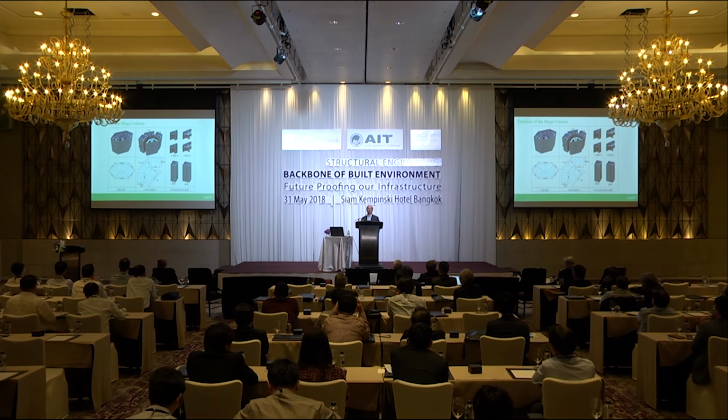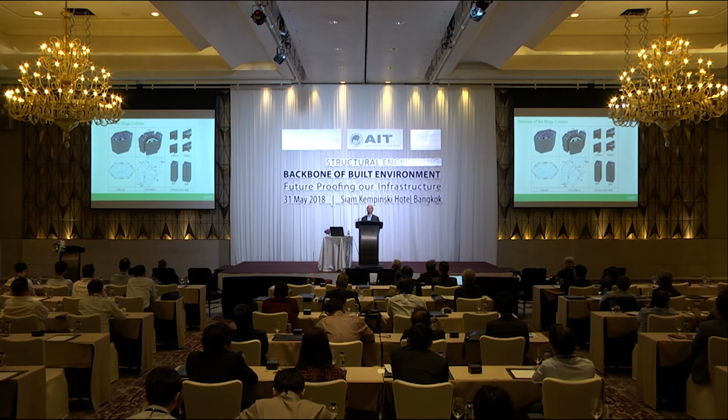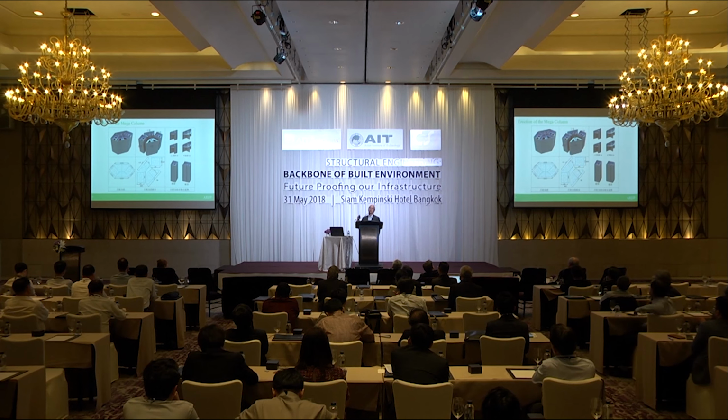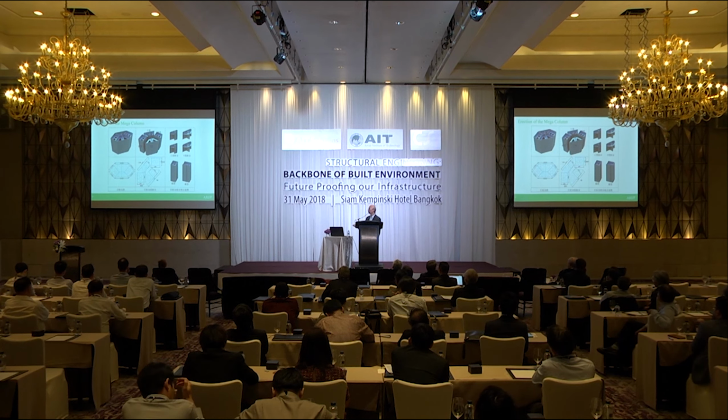So when we design it, we actually design it with a consideration of what we call buildability. We chop the column into boxes and so forth, so that it can lift up at least a story plus, and then they can weld it, and also make sure they have sufficient space for them to weld and so forth. In China, in practice they prefer welding, so we use welding.